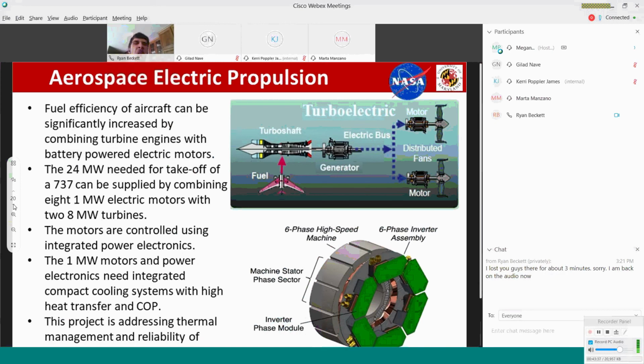And so there'd be these wires between this box that drove the motor and the actual motor. Well, people don't want to do that anymore. They want to integrate all that control directly on the motor. So they want to put the switching devices and the control devices right there on the motor so that they can have one integrated motor system that has its own drive electronics associated with it.